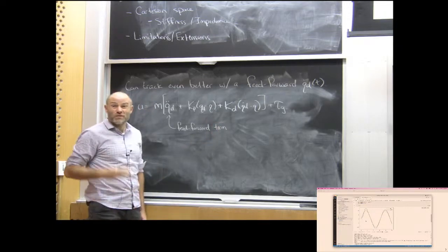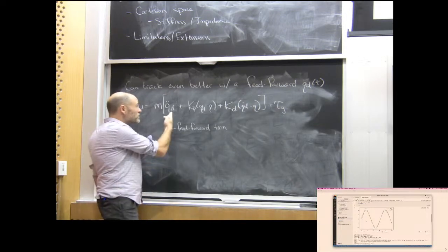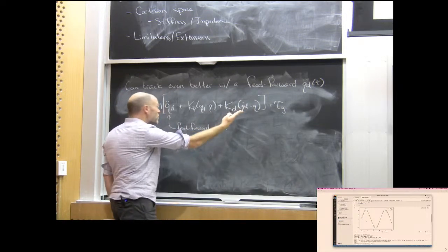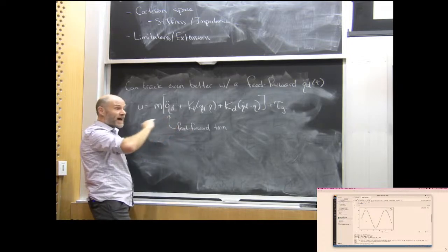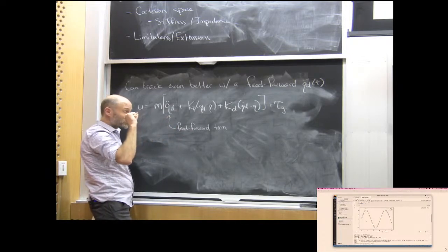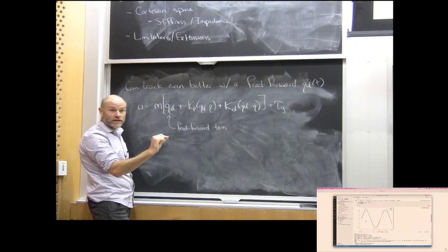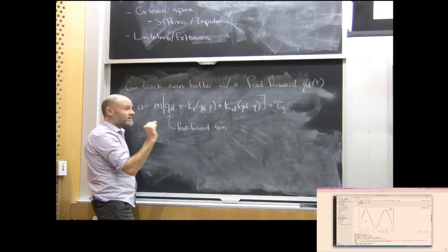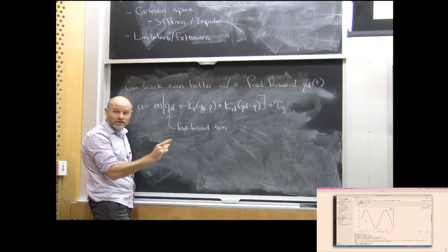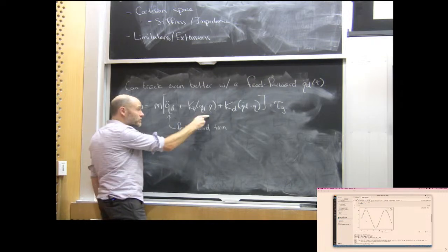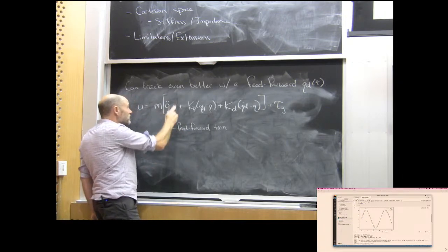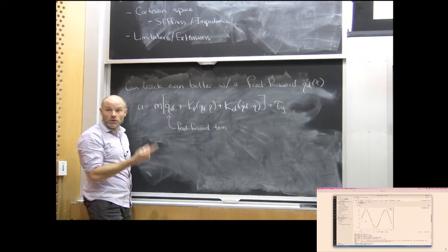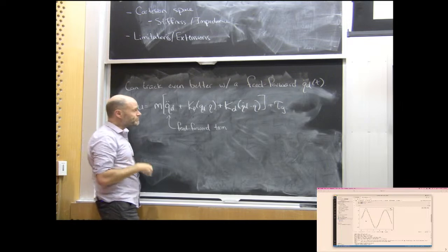And it's fundamentally what you need to do to get around this error-driven control. You want to be able to send it so that if your current system is exactly on the trajectory, it will get the command it needs to stay on the trajectory. You don't have to wait for error to occur to get back towards the trajectory. The way to do that is by giving instantaneous information about where that trajectory is going to go.